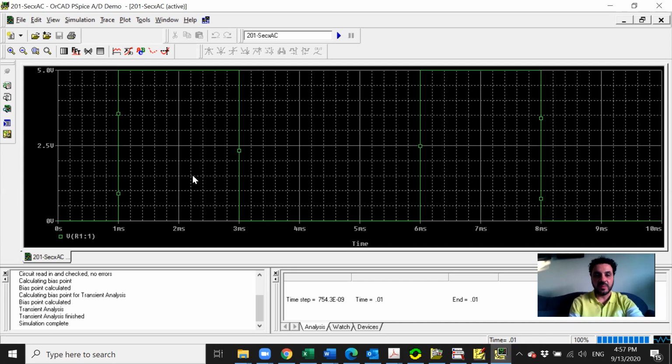Then the period, the whole period is from here up to here. The whole period is 5 milliseconds. It goes from 1 up to 6. So the whole period is 5 milliseconds, okay? The rise time and the fall time, both of them are very small. That's why we don't see them. But we can use the rise time and fall time to generate a triangular wave, as I will show you now.